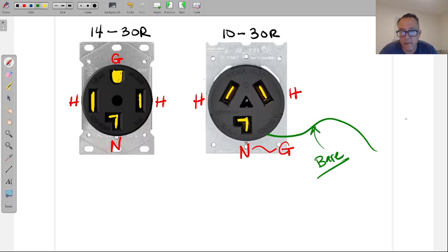I don't know if they've modified and updated, but if you're in America and you're a new electrician these days and you see a neutral that's a wide open copper wire, that could be a little bit confusing, possibly even a little scary. Like, what's going on here? That thing's going to have a load, but it doesn't have a load. Remember what I was talking about with a balance. If this outlet plugged in the dryer were operating at 30 amps on A phase and 30 amps on B phase, there is nothing for this neutral to take back to the panel. So why was the neutral in the dryer situation if it has no job?